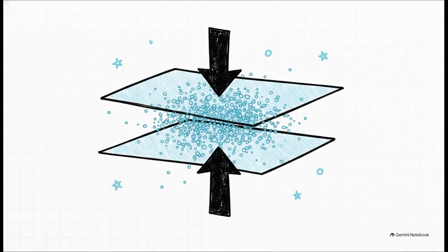So let's talk about the mechanics of how it does that, starting with the minimum zone concept. When a CMM probe touches a part's surface, it gathers thousands of spatial data points. Now, the Y14.5 standard requires us to check these points against specific boundaries. To pull this off, the CMM software algorithm seeks the best fit mathematically. So for example, if it's checking flatness, the software isn't just looking at the points. No, it's actively trying to find two perfectly parallel planes that enclose every single measured point, and then it calculates how close together it can squeeze those two planes. That tightest possible boundary? That's what we call the minimum zone.